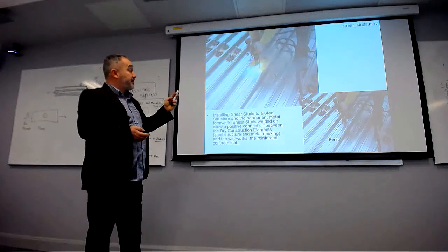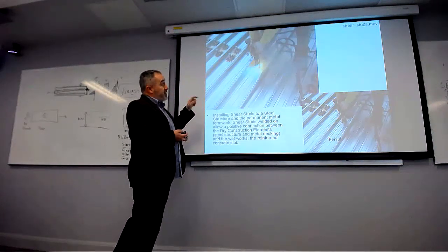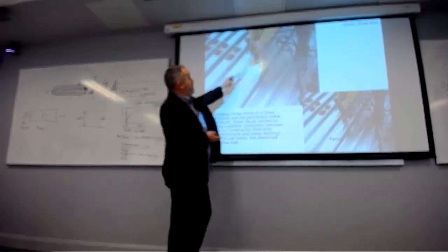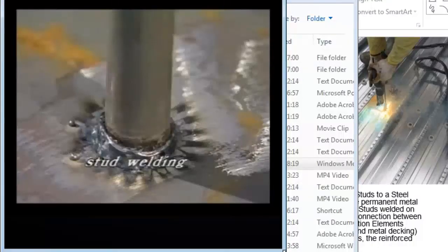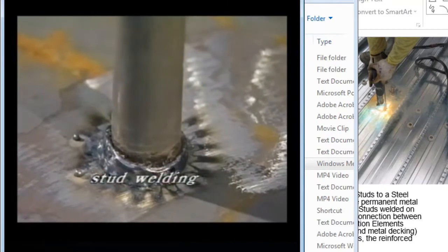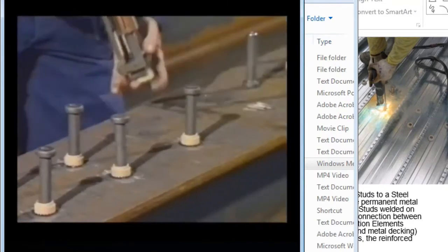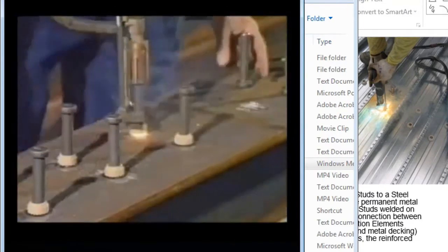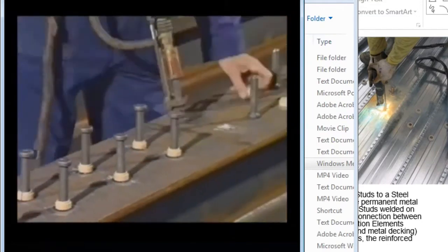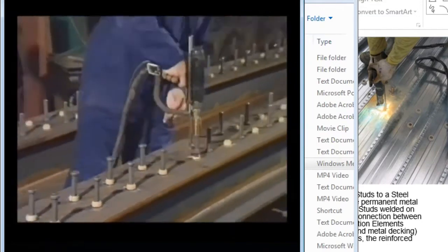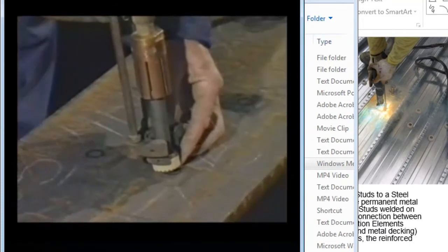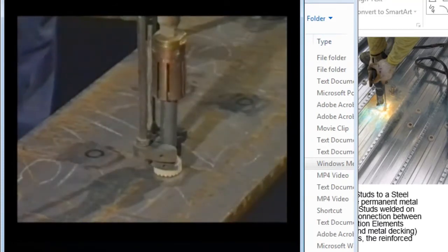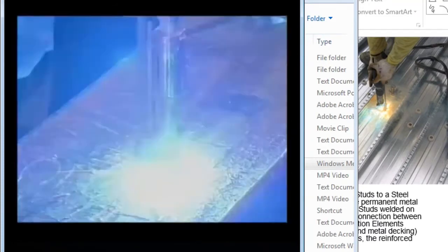This is a picture of somebody putting the shear studs through the wriggly tin. Stud welding is also a form of arc welding. In composite structures, these headed studs form the connection between the steel structure and the concrete. Using a handheld unit, the arc is ignited via contact between stud and flange. Then, the arc heats the stud face and the flange, forming a weld pool.